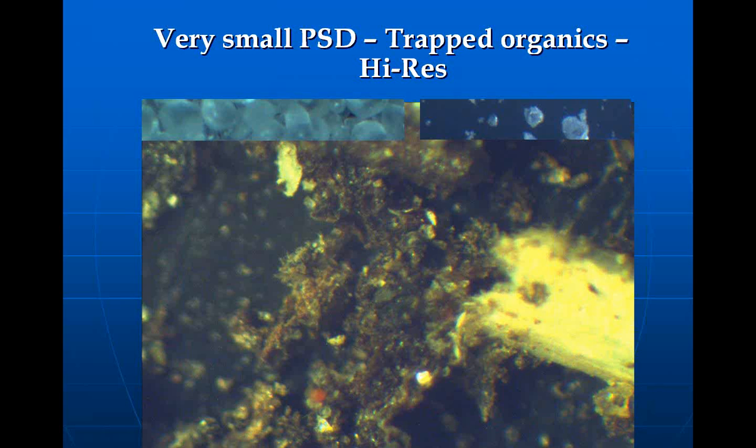So the organics, which are almost the same buoyancy as water once they're decomposed, are in the bottom of these ponds, or they're in the bottom of a device that doesn't screen them out. In this case, we could have missed them with our basket. Remember, I'm using 1/4-inch mesh, so obviously that's a lot of microns. That's about 12 millimeters, I think, so that'd be 12,000 microns. We're not going to catch tiny particles. Things that come to us decomposed, we're not going to catch. So this coconut fiber filter helps. The coconut fiber filter helps us to trap those sort of things.